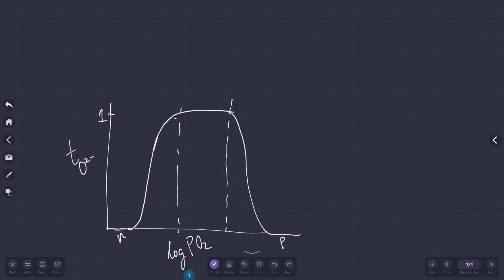Why is this important now? Based on the conductivity data, you can predict. Now you can see that this PO2 range is where the material will be purely oxygen ion, that 100% oxygen. And that's the requirement for any electrochemical cell for an electrolyte.